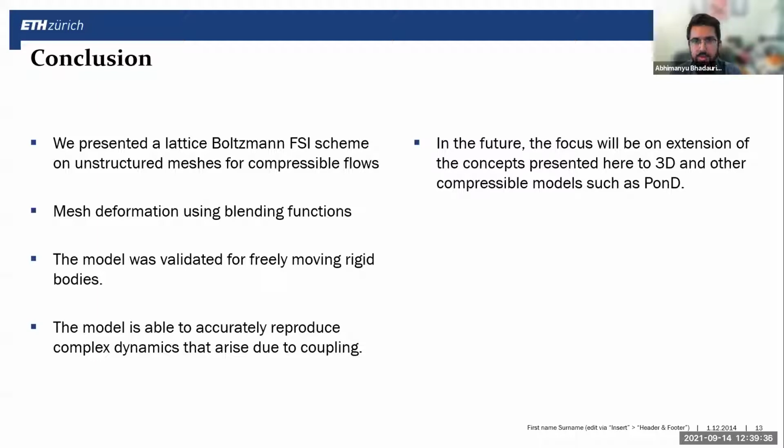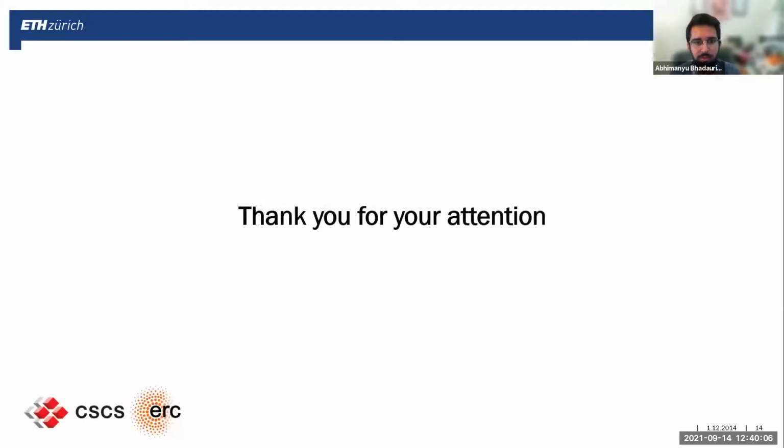And besides that, in conclusion, we presented our Lattice Boltzmann FSI scheme on unstructured meshes for compressible flows. The mesh deformation was handled by a very efficient and fast blending function approach, going away from a PDE solution. And then we validated the model for a variety of rigidly moving bodies. And we were able to accurately reproduce dynamic phenomena that have been reproduced in literature. Thank you for your attention.